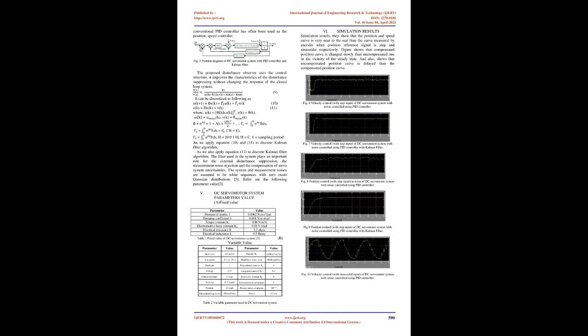Then we must resort to experimental approaches to the tuning of the PID controller 6. In presenting the various tuning techniques, we shall assume the basic control configuration of Figure 3, wherein the controller input is the error between the desired output, command, set point, and input, and the actual output. The error is manipulated by the controller, PID, to produce a command signal for the plant according to the relationship 7.